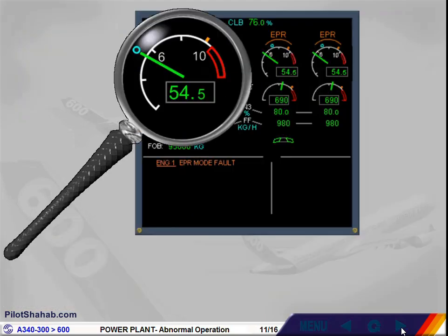On engines 1, 2, 3 and 4 N1 indications, the blue circle indicates the thrust lever position. The amber index indicates the N1 max, full forward position of the thrust levers. The amber index is not displayed when in N1 unrated mode.